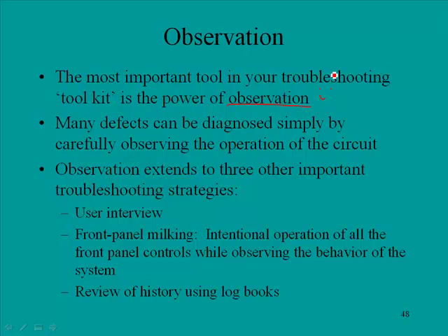Sometimes it's what you smell that tells you a lot. Those of you that have been around this business know that there's just that smell of burning components that tells you something is very wrong. Sometimes you'll even hear sounds that shouldn't be there. But anyway, observation is very important in diagnosing faults.